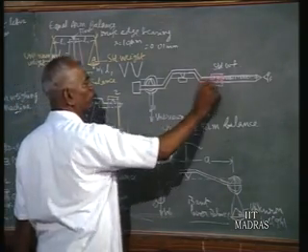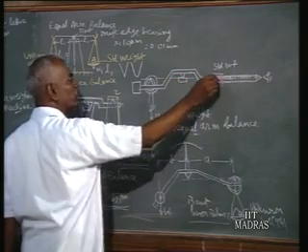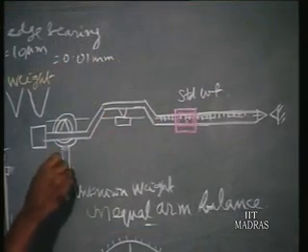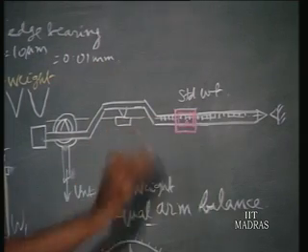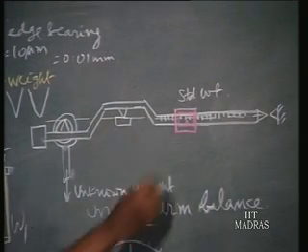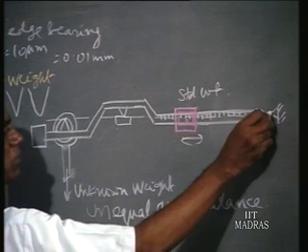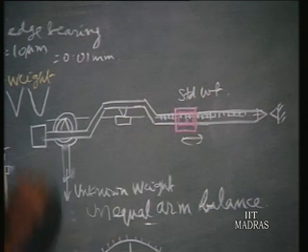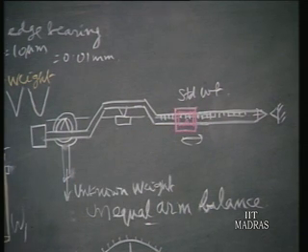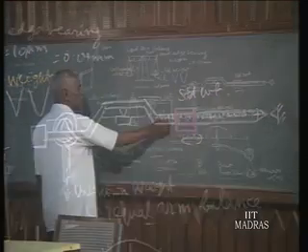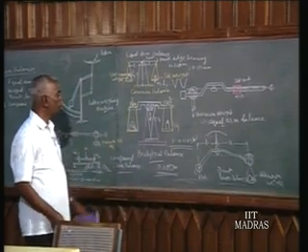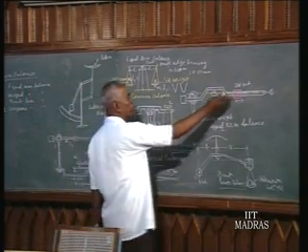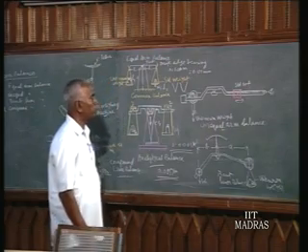Here, because of the longer arm, with a smaller weight we get a larger moment, and on the other side a larger load gives a smaller moment, and we can equalize them. We move the weight to and fro until the end tip of the lever stands against the reference mark. Then we take the reading of the weight, and that is how it is done. One advantage over the equal arm balance, where the unknown weight and the standard weight should be equal so we would need standard weights covering the full range, is that here a smaller weight lets us compare a larger weight.